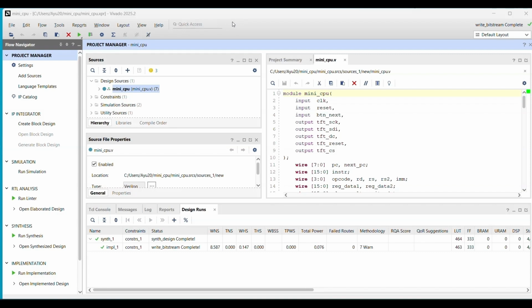Every instruction in my project is 16-bit. All arithmetic works on registers R0 to R5, not memory directly. Each instruction completes in exactly one 50 MHz clock cycle. Only 6 opcodes are needed for the full demonstration.